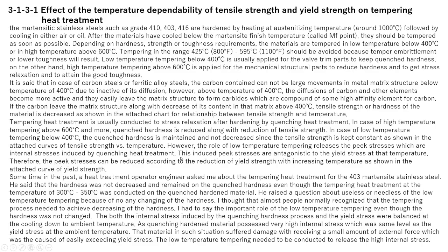So again, this induced peak stress is antagonistic to the yield stress at that temperature. Therefore, the peak stress can be reduced according to the reduction of yield strength with increasing temperature, as shown in the attached curve of yield strength.